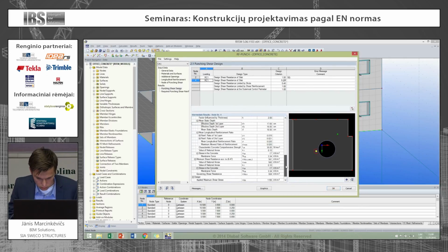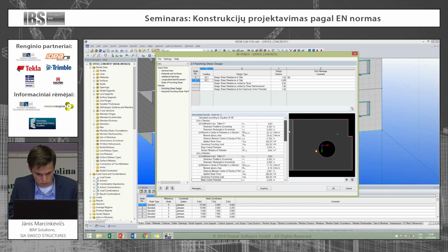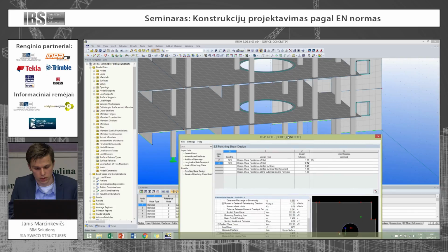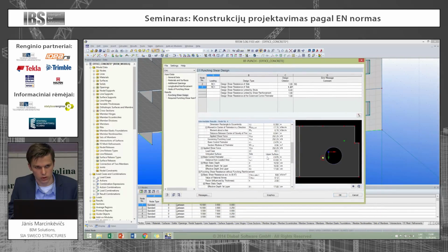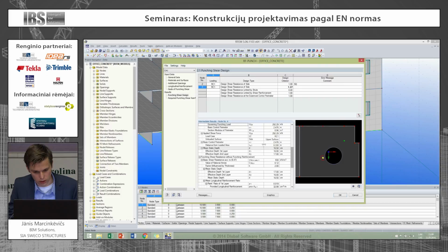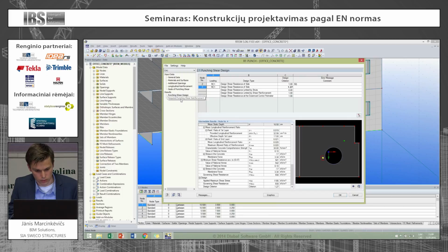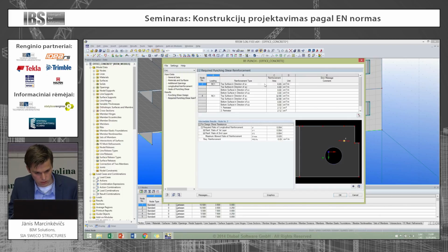There you can also see all the coefficients. You can modify the ratios of the flexural reinforcement. Basically, this module, if the slab has been calculated, will take those values of the reinforcement and feed them in this module. Or you can add that manually. There you can see the control parameters. All right, and concrete capacities without the reinforcement. And then we can go to the reinforcement.